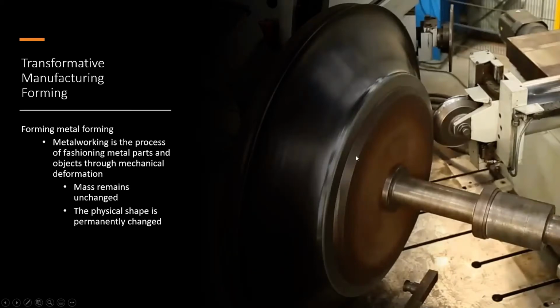So in the trash receptacle world of site furnishings, you often see this type of process used. That's what this picture is depicting here. You start with a disc of sheet metal, and it spins along this giant axis incredibly quickly. Then you use a variety of tools to shape these into trash receptacle tops and lids. They're called spinnings, is the term used for these types of tops. So that's an example of metal forming in the site furnishings world.